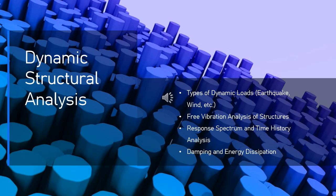3. Hysteretic damping. In hysteretic damping, the energy is dissipated through internal friction in the material or structure. This type of damping is commonly observed in materials undergoing plastic deformation, e.g., during large-scale cyclic loading like earthquakes, or in structures with nonlinear behaviors. 4. Structural damping. This involves energy dissipation mechanisms intrinsic to the structural elements, such as the internal damping of beams, columns, and joints, and is generally represented by the sum of various damping effects.